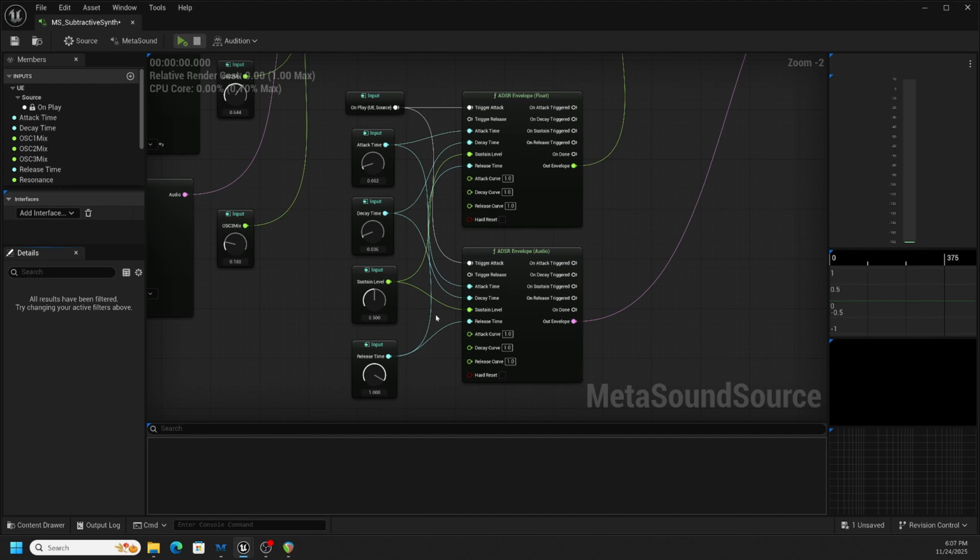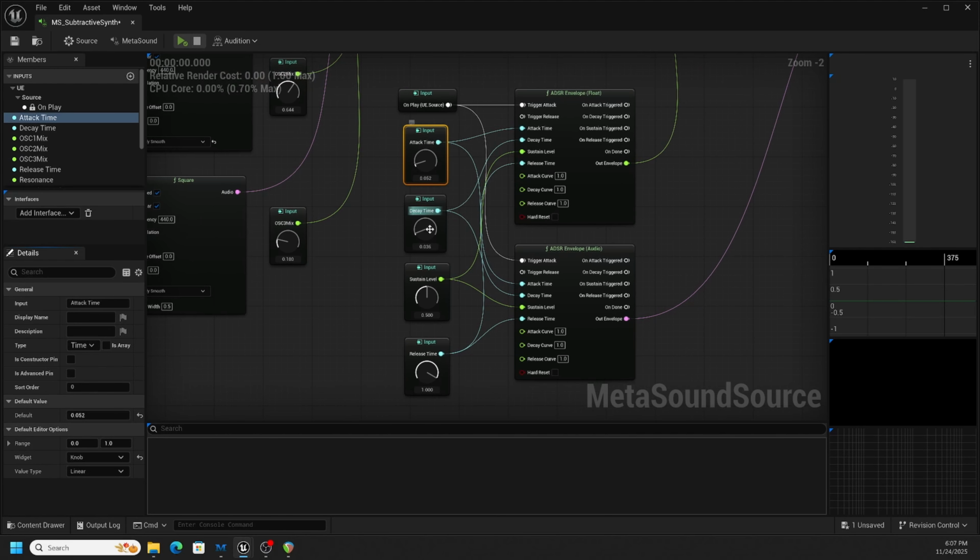That all looks good. And now, before we go too much further, we need to set the default values of these. And I've had difficulty getting exactly what I've wanted with these numbers here. I'd like to have 0.01 as my lowest range on my attack time. On a digital system like this, we never want 0 as our attack time. We're going to hear pops as the oscillator pops open, and amplitude and the filter and so on. So having 0 for your attack time is just generally a bad idea. So I would like to have that at 0.01 so we can never bottom out there.